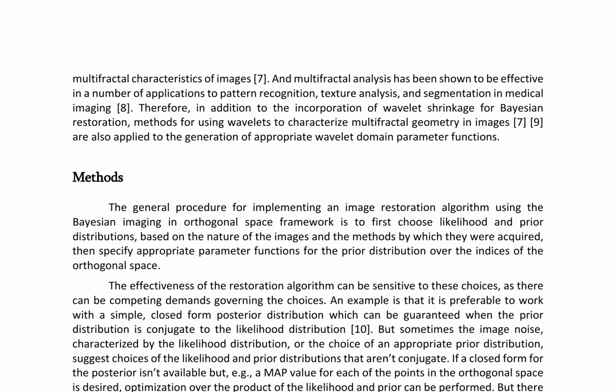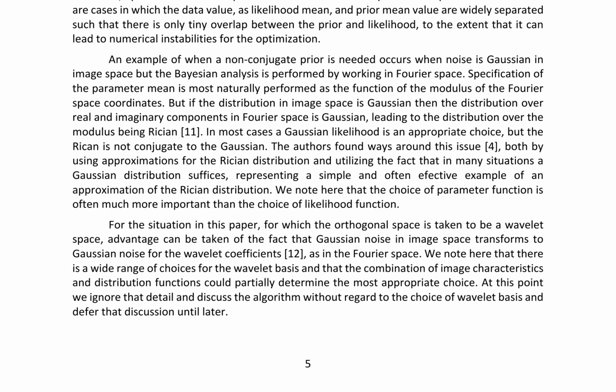They propose using wavelet shrinkage properties to capitalize on the sparse representation of typical signals in the wavelet domain, assuming that most coefficient values less than a predetermined threshold represent noise and can be zeroed, while those greater than the threshold represent signal and should shrink by some amount, also specified by the threshold. The authors suggest employing the thresholds proposed in 6 and 9 for this purpose.